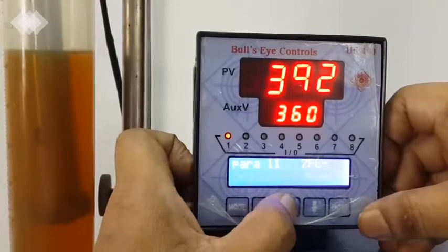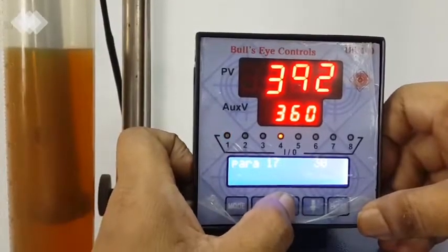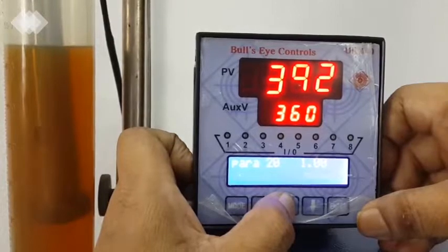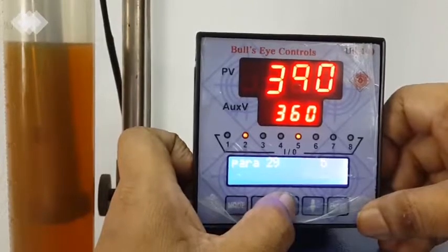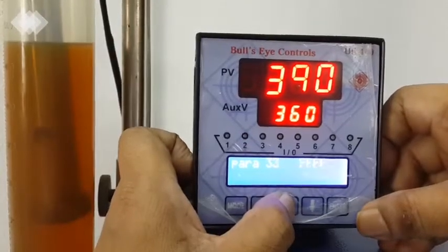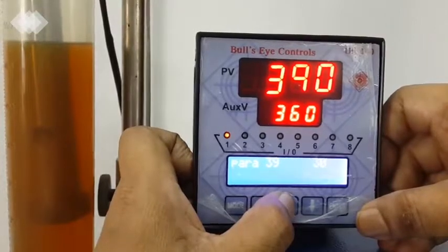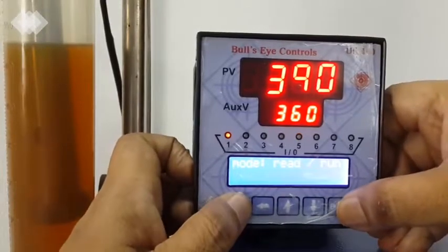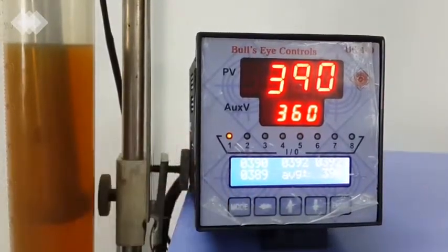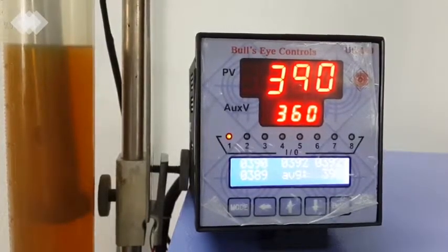They include the sampling period of the viscosity reading, conversion factor, control parameters of the viscosity and temperature, amplifier characteristics, as well as the alarm limits for viscosity and temperature, PC interface parameters, and so forth. This list is given in the manual, so you can go through that and understand the same. The parameters are not supposed to be changed frequently. For a particular application, generally once you set the parameters, it is supposed to run all along.